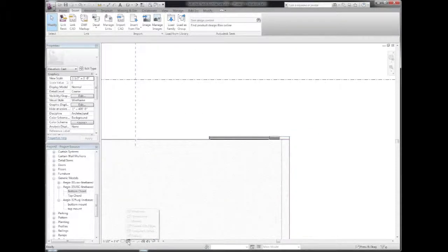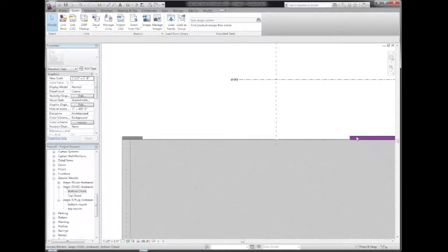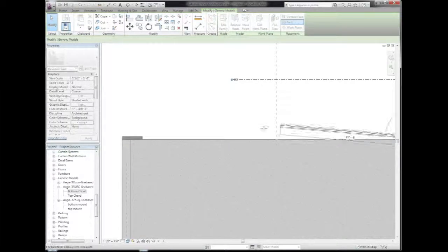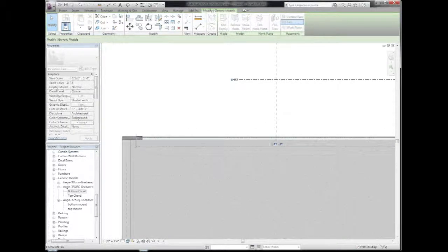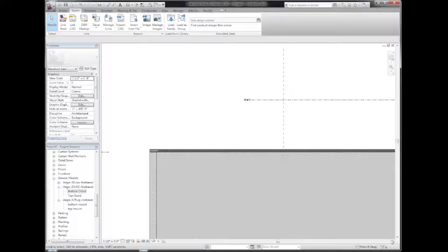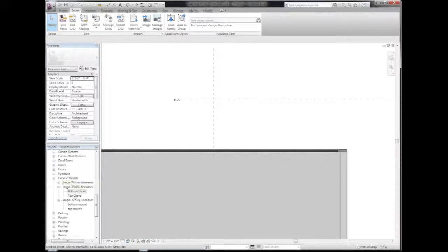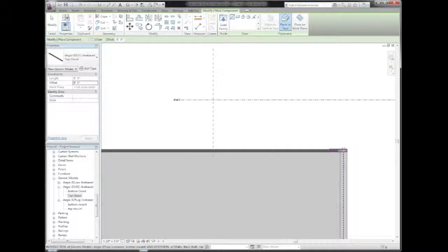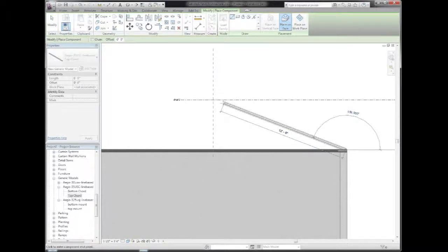So I'll switch back to my shaded view and grab that bottom UltraSpan cord and use its control anchor to pull it all the way across so it's approximately in the correct position. The next element will be the top UltraSpan cord. So I'm going to grab the same cord component but choosing the top cord option. Touch the face of this element and drag it up approximately where I think it needs to be. I can always come back and adjust it later.